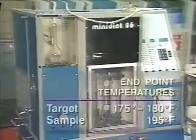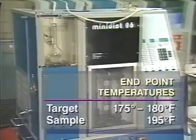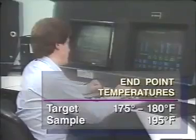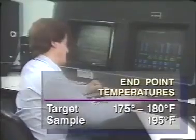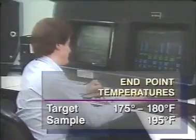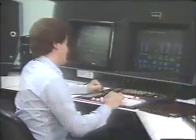Suppose lab tests show an overhead product has an end point 15 degrees higher than called for by specifications. An operator quickly increases the reflux rate to remove heavy material from the overhead product. In this situation, has the operator used logical thinking and made the correct adjustment?